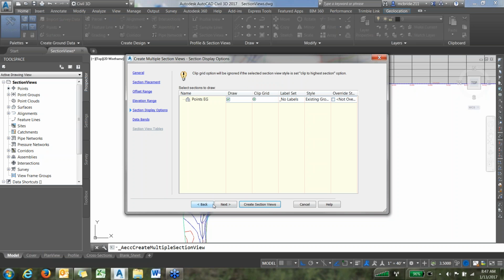Okay, this is the point where you have to make sure that you're sampling the right surfaces. So at this point, you may have 3 or 4 different surfaces out there. You just want to make sure you're sampling the right one. What I want is the surface that has the existing ground that's out there before we do any work, and then I want the finished ground, the one we designed, where it's got the shape to where it should be once it's properly constructed.